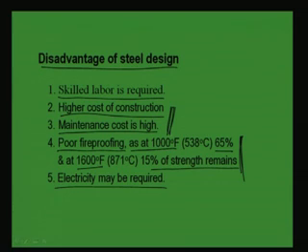Yes, it depends on what type of building we are going to build. If we need a more column-free area, meaning more area without columns, then in that case we should go for steel, like in an industrial building. And if it is a tall building, then for concrete, because of its own self weight, the area of the columns will become very high. So, we may not be able to go for a high-rise building in concrete. In that case a steel structure will be required. So, we have to see both cases and optimize which will be better.